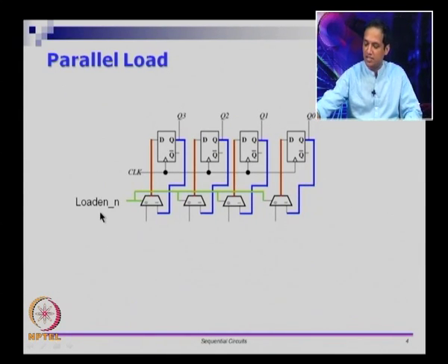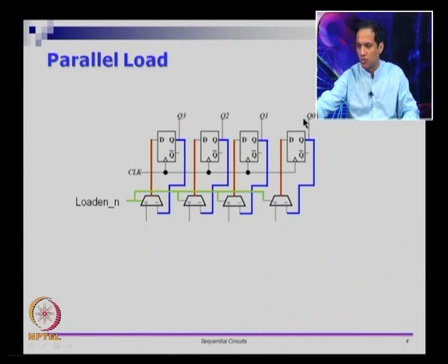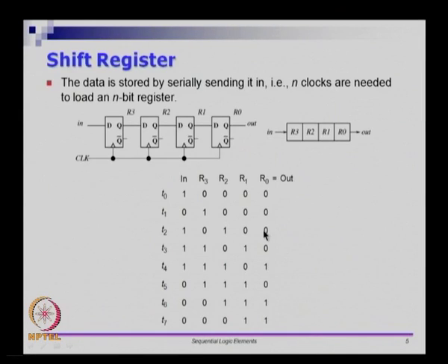So it is a fairly interesting setup and it gives you one clock cycle access to the data. And the key thing is Q3, Q2, Q1, Q0 are still retaining the capability of being read in one clock cycle. So I can read all of them in one go. So D3, D2, D1, D0 is plugged in at these pins and we are done.